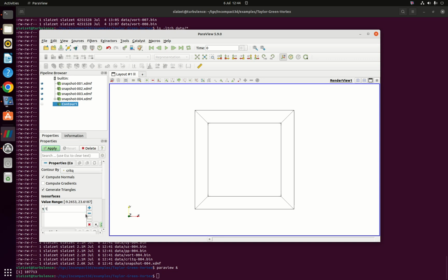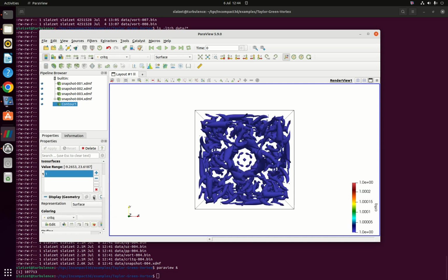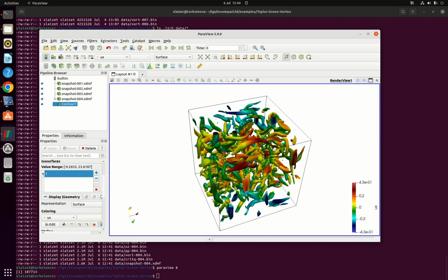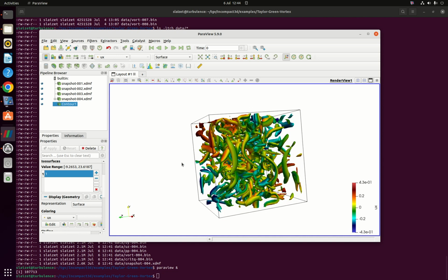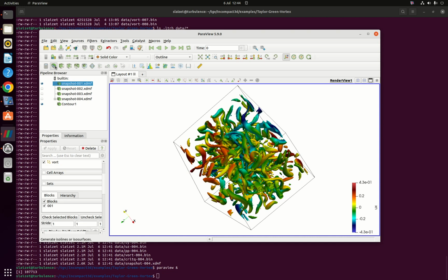with the Q criterion, it's a good one. I'm going to use a value of 1. And you can see you have a nice, I'm going to do the coloring. So I'm using the rainbow desaturated color code, and you can see you have a fully turbulent state. So that's quite nice. So this is how we can look at the instantaneous field.